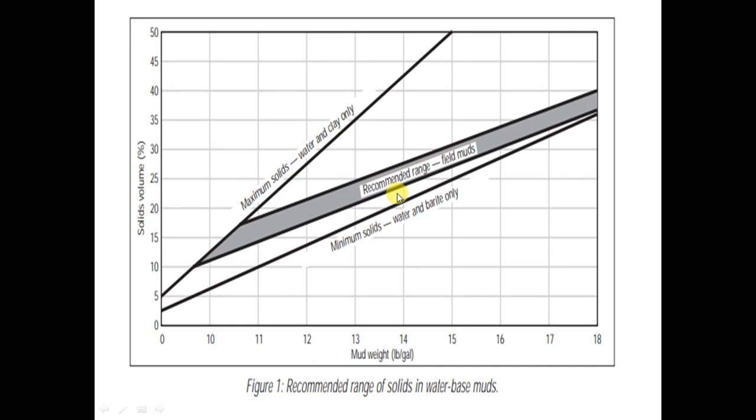Someone may ask me, can the solids be lower than the required? Yes, if you are making dilution, or if you are adding salt to the mud, the salt will increase the mud weight, and so the solids will be very little. So take care of all these points because they are controlling the solids.